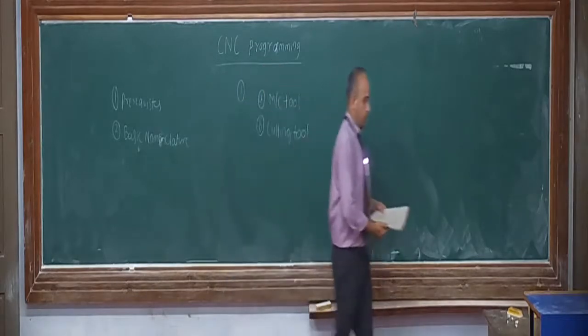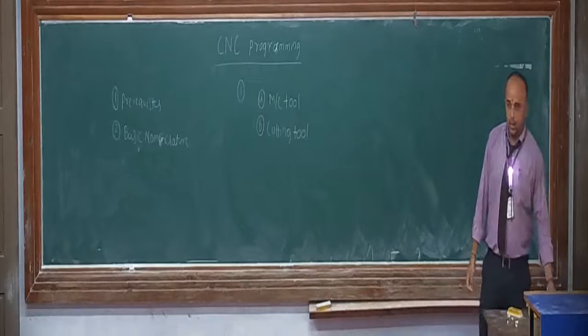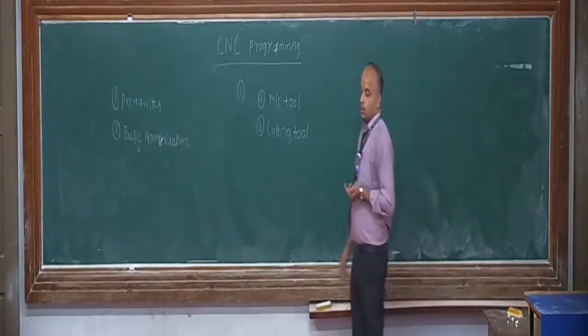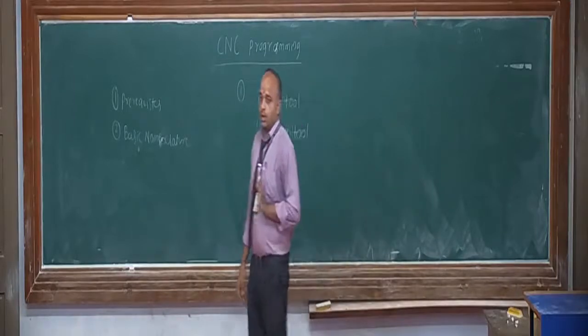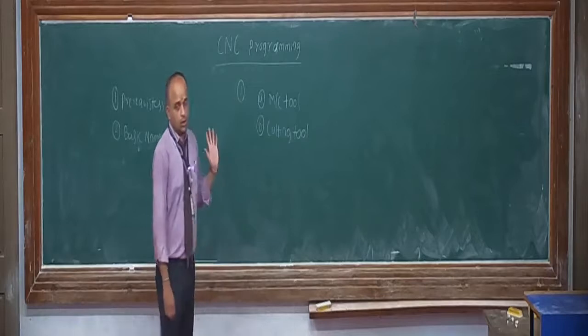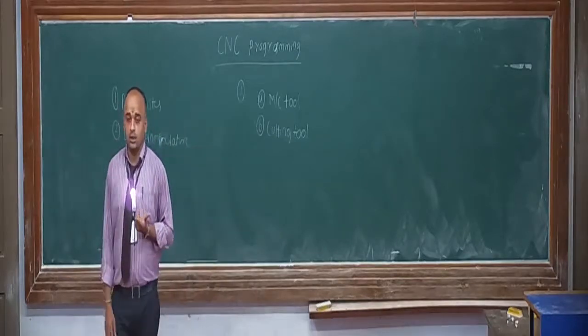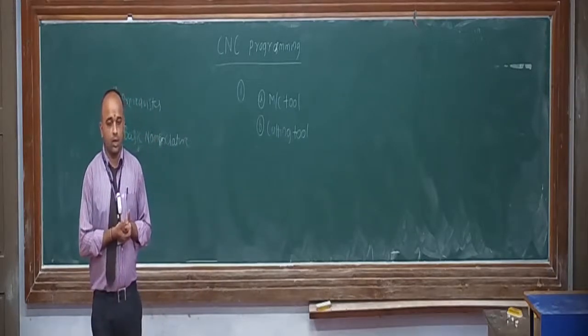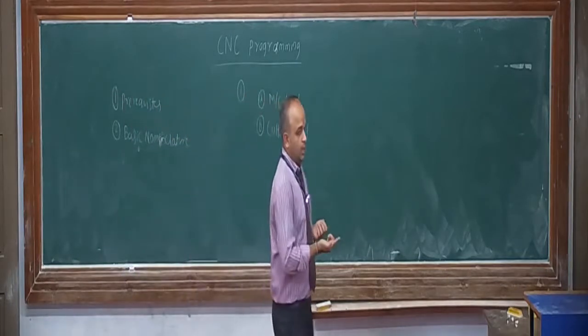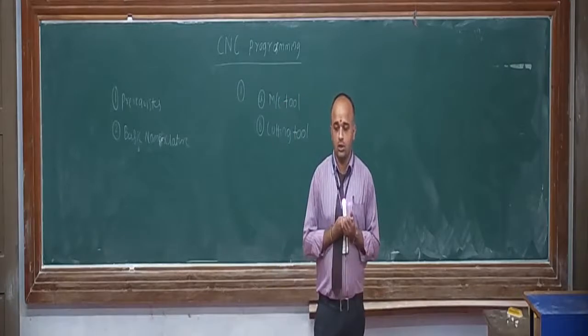So the second prerequisite that is necessary is called the cutting tool. Now, what do you mean by cutting tool? Cutting tool is nothing but the tool which will be used in order to cut the workpiece to the required sizes. Now, in case of lathe machines, we have seen HSS, that is high speed steel, wherein a high speed steel tool is taken, put on a grinder, and we get the different rake angles. You have also seen the nomenclature.